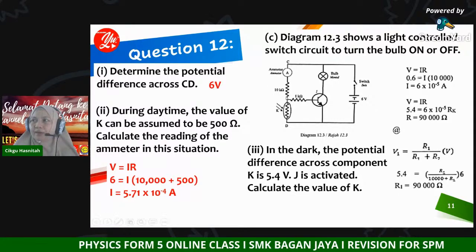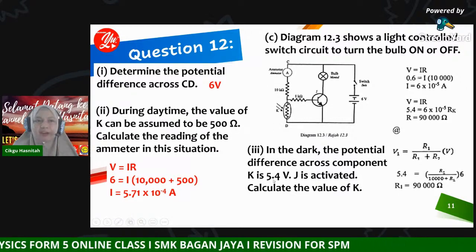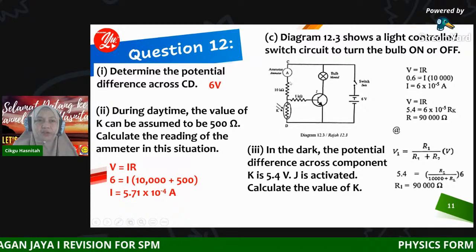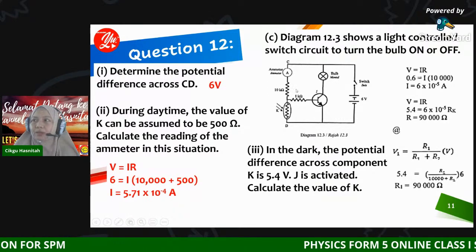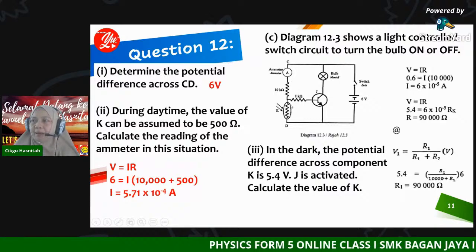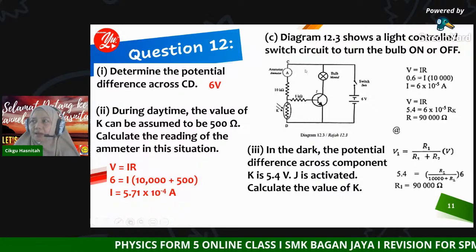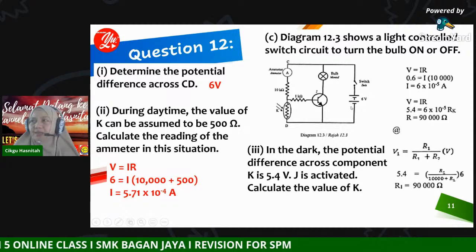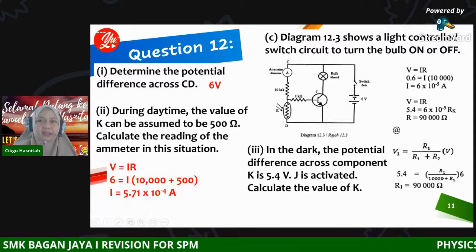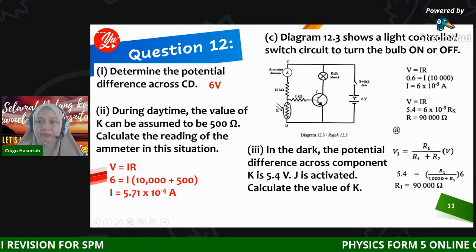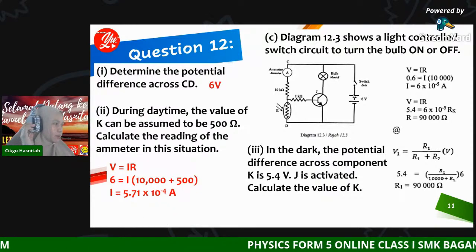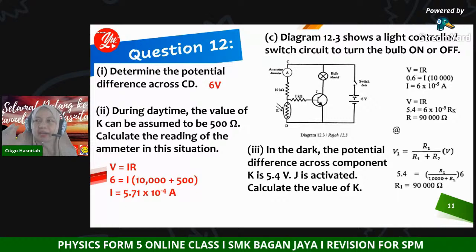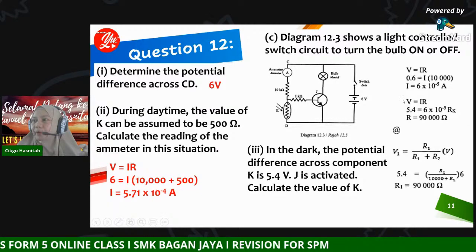Down here the voltage is 5.4, and the voltage up here is 0.6. If you total them, 0.6 plus 5.4, they will give you a total voltage of 6, similar to the external voltage supply. Okay, are you clear now, Kwang Yu? Is it clear? The rest of you, are you clear why we use 0.6 here?